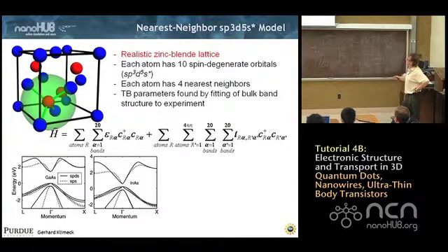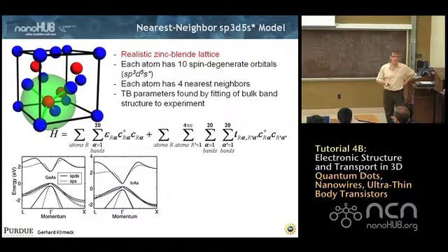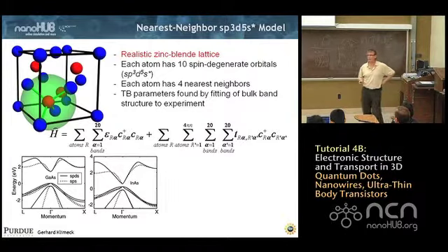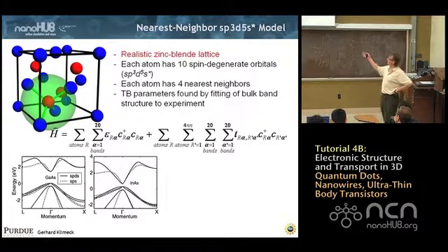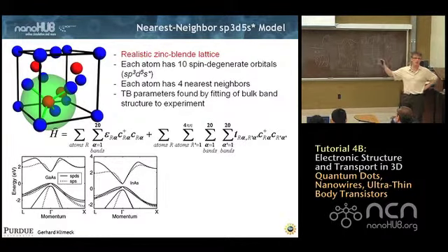And so here you see gallium arsenide, and here you see indium arsenide, and in the dashed lines you see an sp3s* model, and in the solid line you see an sp3s*d5 model. So typically, when we work in indium arsenide, gallium arsenide these days, we use the sp3d model because it gets the excited states and the full Brillouin zone of the material quite nicely, also as a function of strain. So that's built into the model. Right? We don't stick that in anymore.